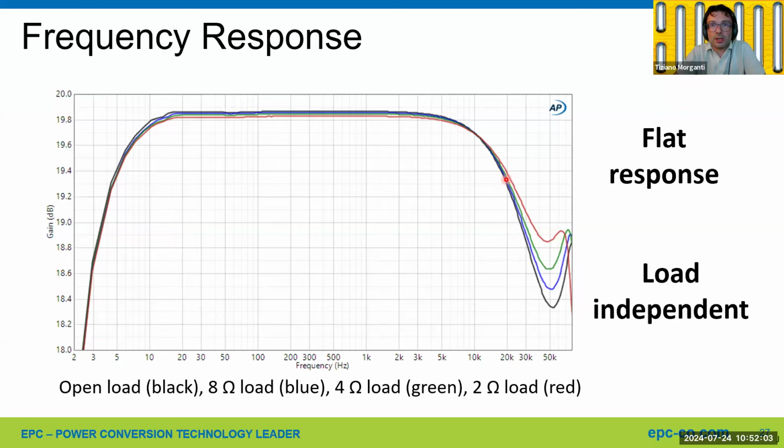The second reason to do so is, for the same reason, you become more independent from the linearity of the output filter, so you can get some correction of the distortion induced by the output filter, and so you can get, in general, a better audio performance in terms of THD and noise. And of course, not all the amplifiers or solutions can be implemented with this kind of feedback, but we believe it is one of the best solutions you can adopt.